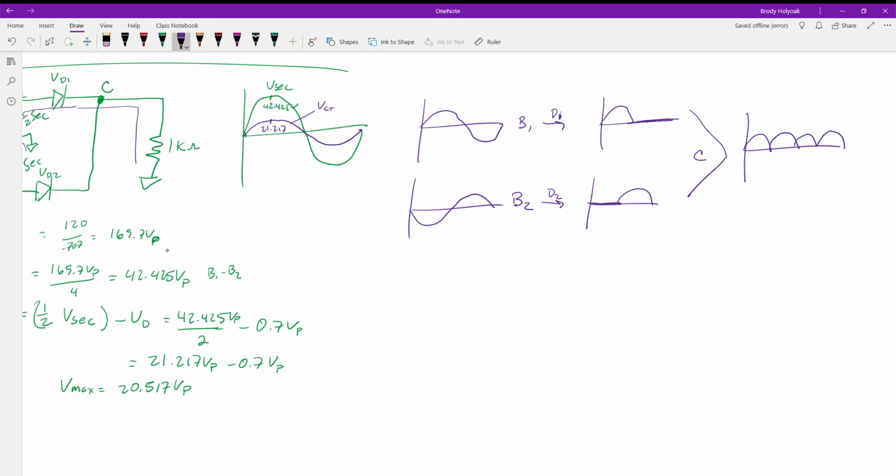So when we're talking about frequencies, remember, it's the instances of a waveform that pass per second. In this case, we're looking at how many times the peak passes in the same amount of time. We knew that this was a full wave from there to there. So we went from 60 hertz to a signal that we've doubled. Now we're going at 120 hertz. This is going to be important when we get into some of the filtered stuff.